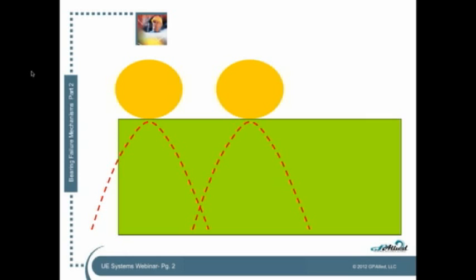So we're asking ourselves then, how often does a given spot on the inner race get compressed, relieved, compressed, relieved? Well, it's about 21 million times a day, or if that machine ran 24/7, it'd be about 7.5 billion times per year. So mechanical engineers in the audience understand that there is no metal that can handle cyclic fatigue forever. That all metals, regardless of their composition, will and do have some cyclic fatigue limit. And what happens is we start to get that subsurface cracking that we talked about last time, and we'll show some pictures of it here in just a moment, right?